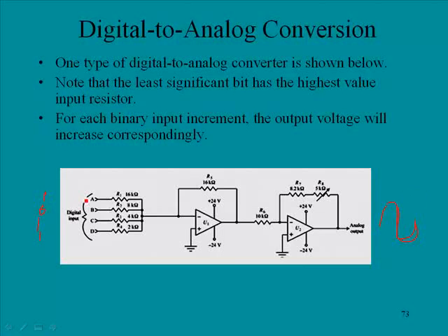And so if we were to stretch this out, maybe if you had 1, 1, 0, 1, this first bit would be the least significant bit, and then D here would be the most significant bit. We're going to look at this in a schematic on the next screen. But for the moment, here we have our inputs, and we call these weighted inputs because the resistors here are weighted in proportion to the input value.